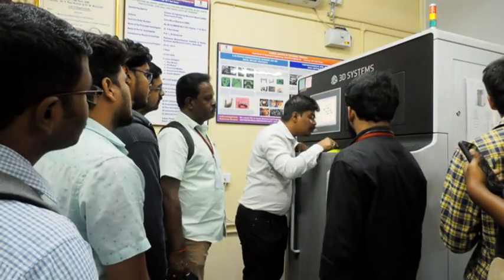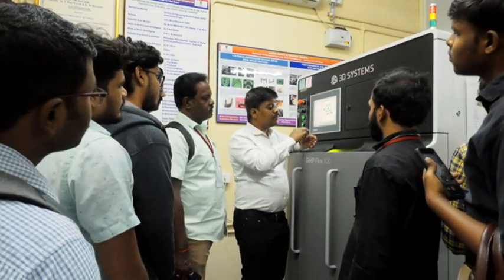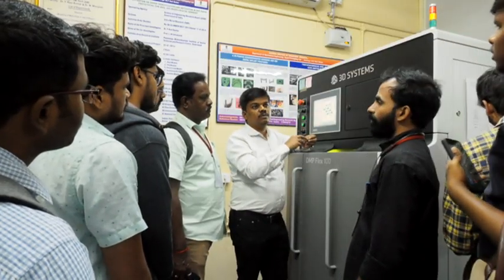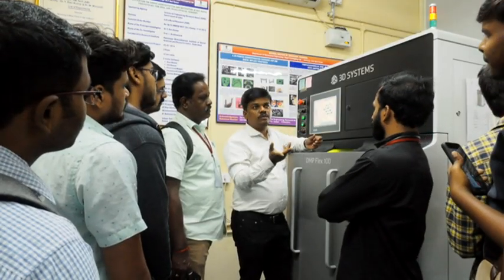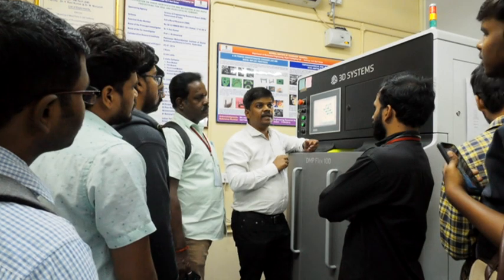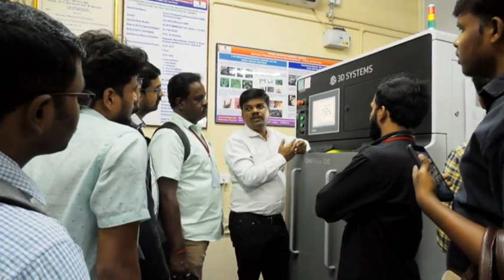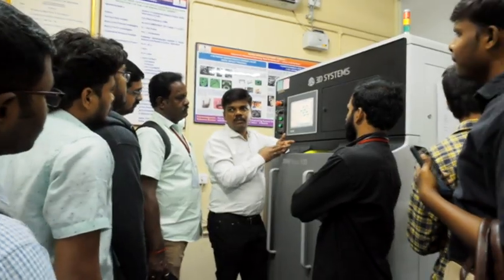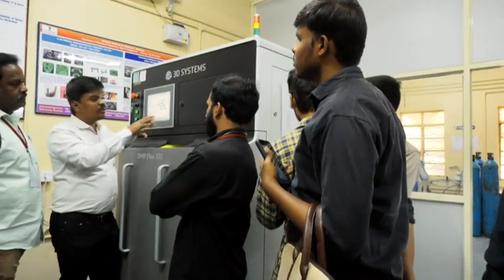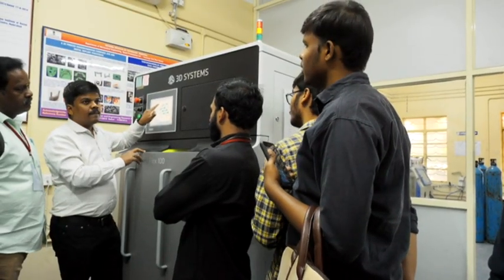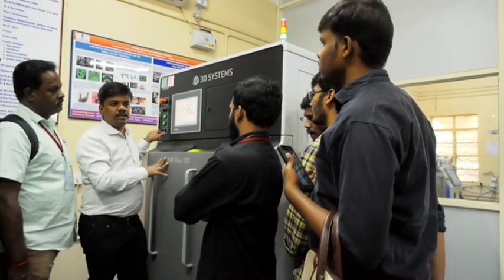You see some spattering is coming. Spattering means while melting, some powder particles are ejected from the melt pool and shifted onto another area. That will not be used because it has already absorbed the heat. We cannot use that. If used, you end up with defects. You cannot melt properly, and there are oxidation problems and all. That's why we use only the surrounding powders which are not melted, and again receive, reheat and then use them.